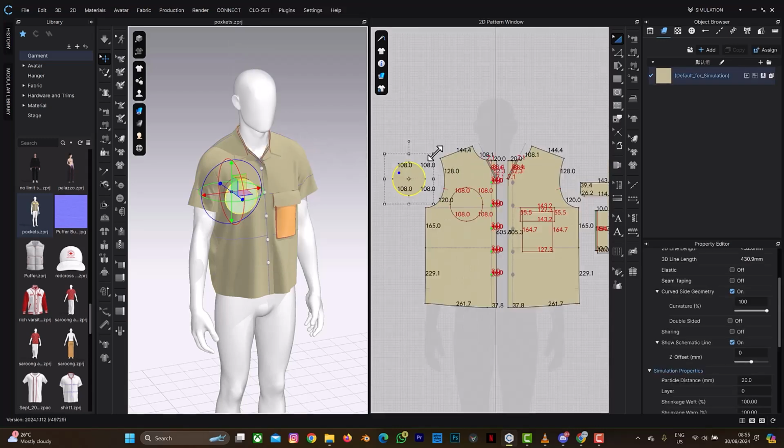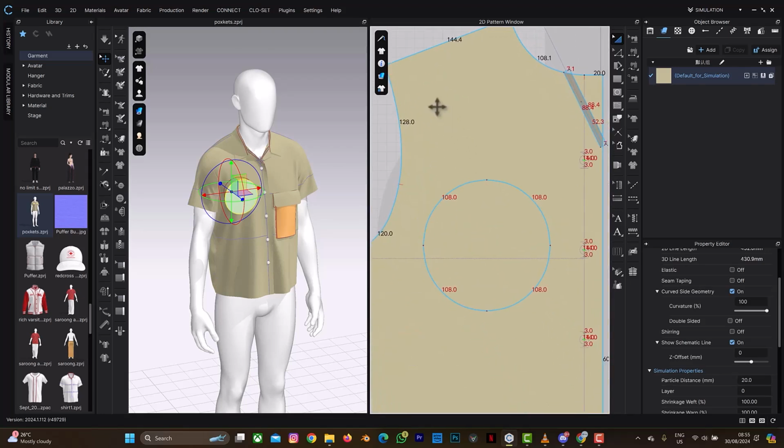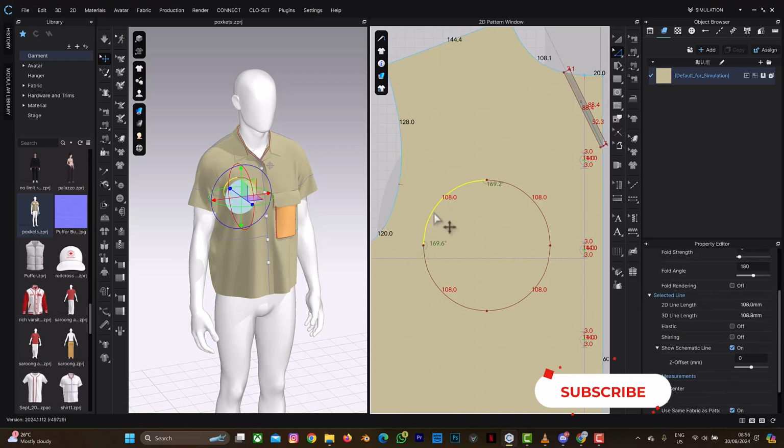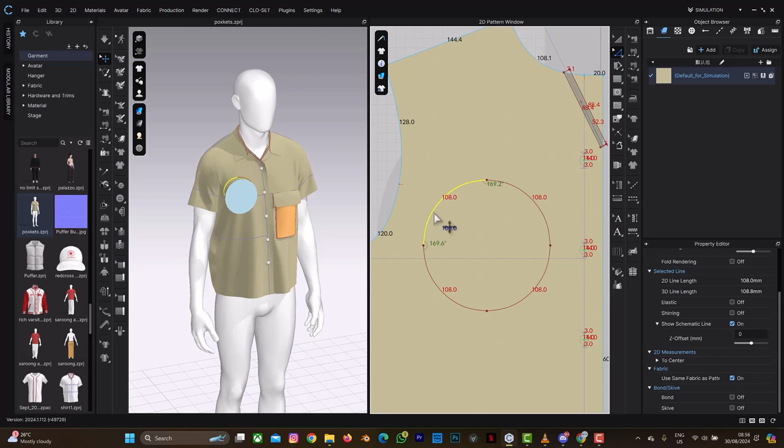Yeah, so let's go back to what we were saying. So after turning on show length, for us to know the total length of this, what I'll do is select Z to select line. Z is the shortcut to select line. So select this and focus on the blue number, or the blue measurement, the blue value, sorry.